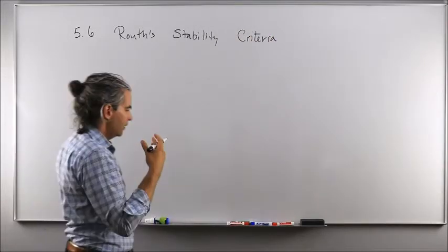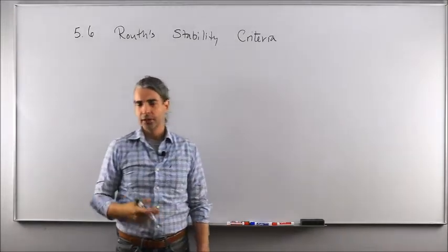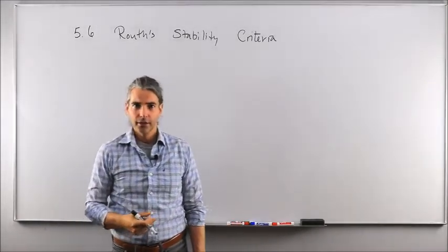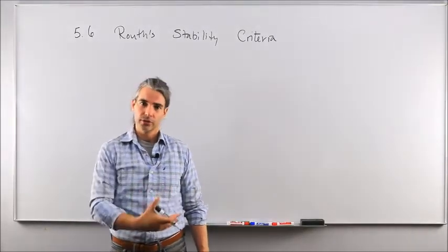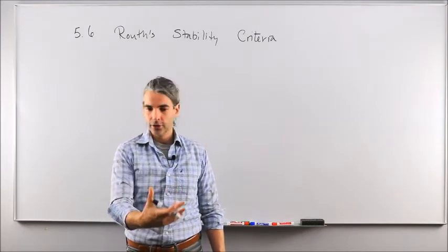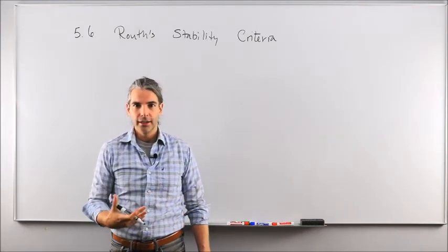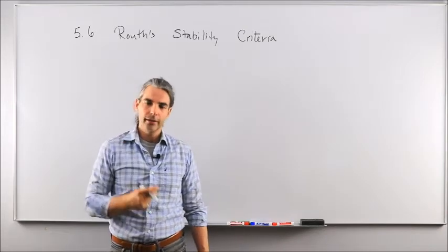Well, you may say, well, hold on a second. We know already how to assess the asymptotic stability of any transfer function, right? All we have to do is to solve the characteristic equation for the roots, or look at the denominator of a transfer function and look at whatever cancels the S terms, right? The poles of the system. Yeah, correct.